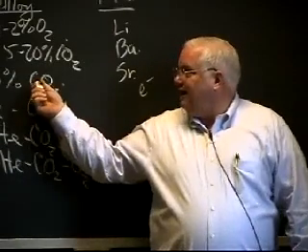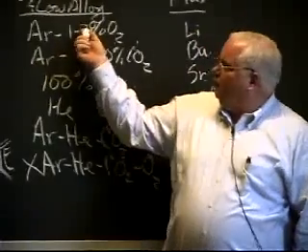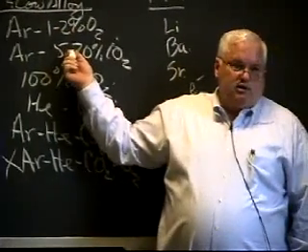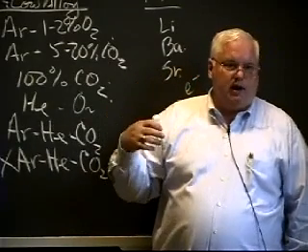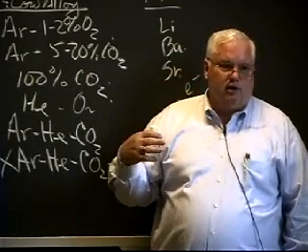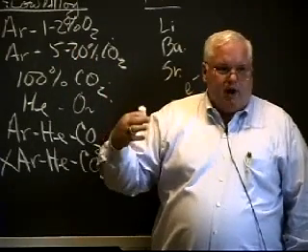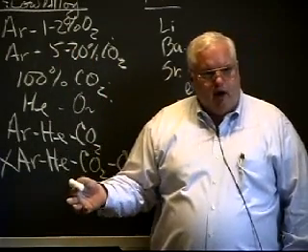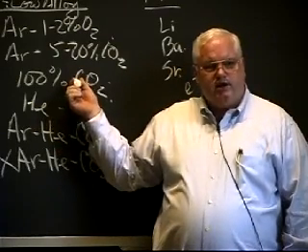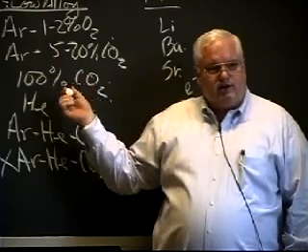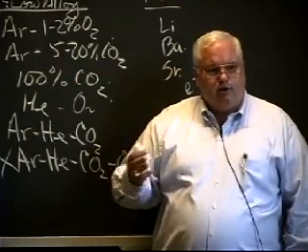It turns out a welding electrode in carbon low alloy steel for these shielding gases might have 1.5% manganese and 0.5% silicon in the electrode. You'll oxidize some of that away, but you end up with 1% manganese and 0.25% silicon in your final deposit. In order to do that here, you've got to start with 2.5% manganese and up to 1% silicon in order to get that same deposit chemistry, because all that extra oxygen is oxidizing away some of your alloying elements.